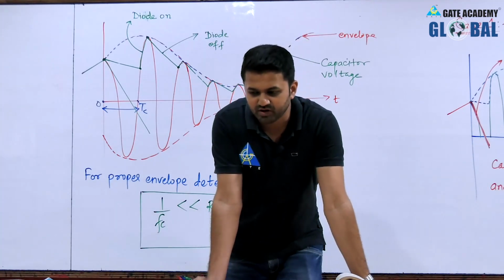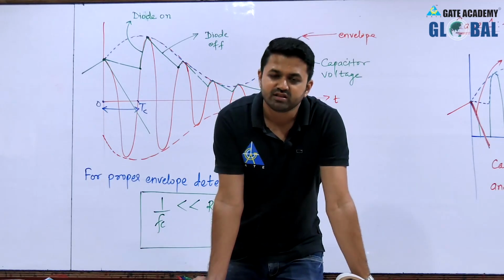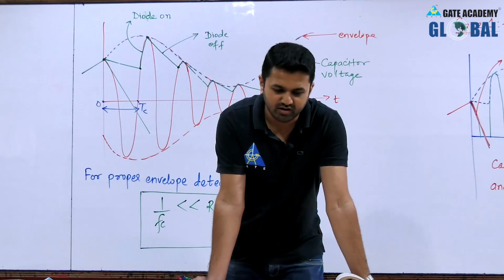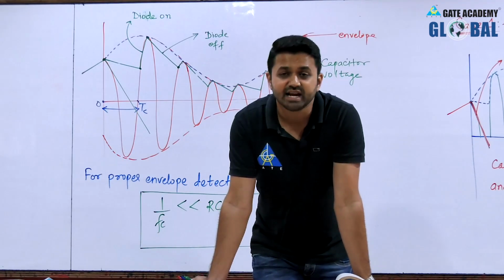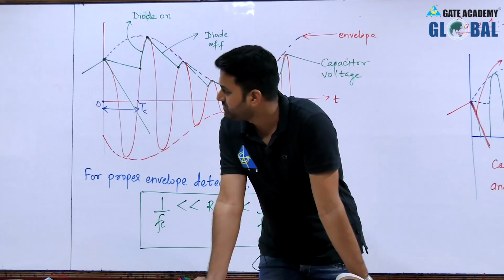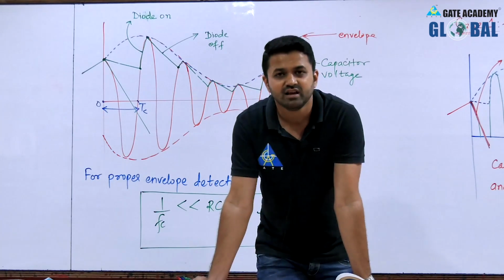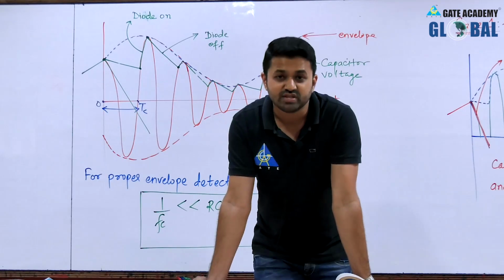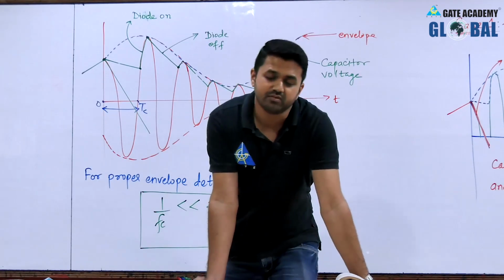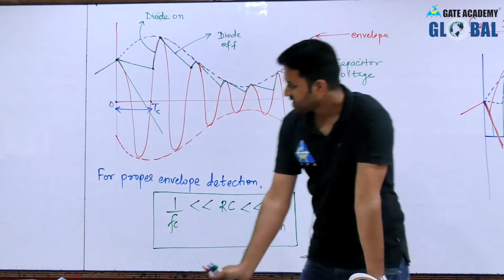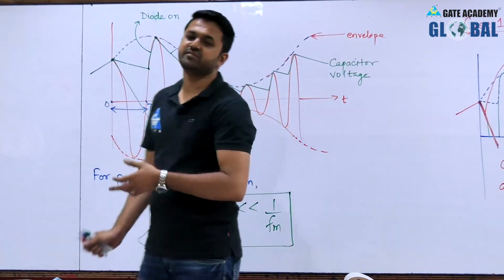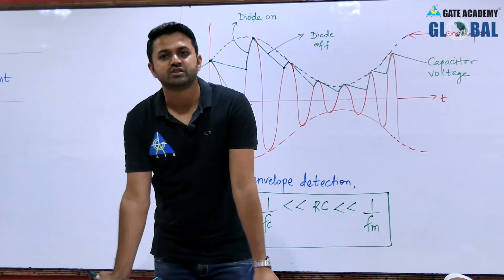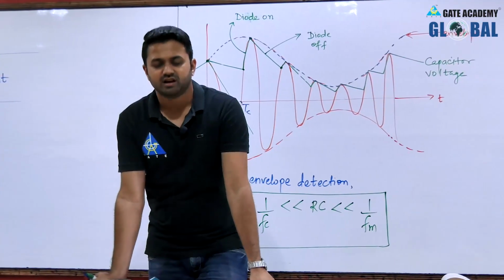But in case of modulation index equal to 1, the minimum envelope E minimum will be there and we will get the information. That's why we can make the modulation index equal to 1 also, which gives maximum efficiency. Now we can derive one more condition when we consider a single tone sinusoidal modulating signal.